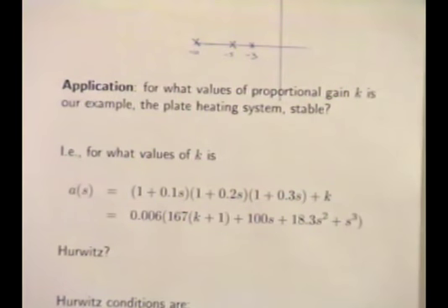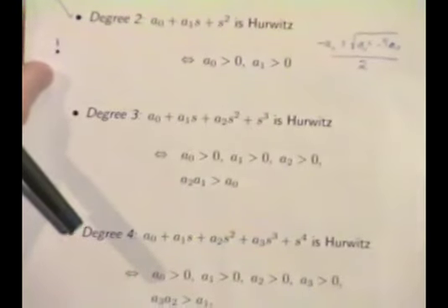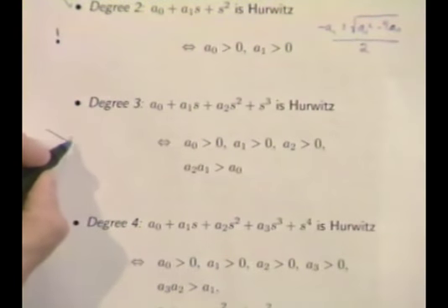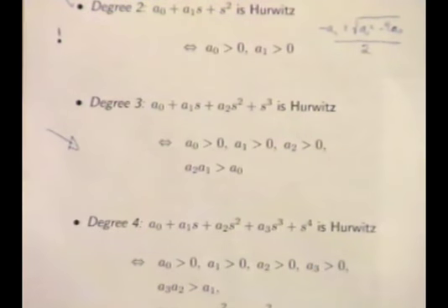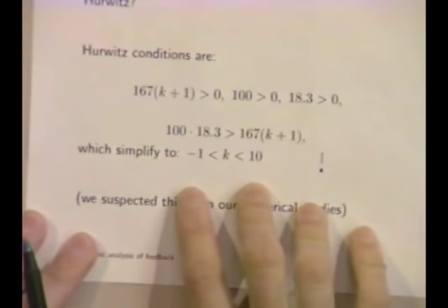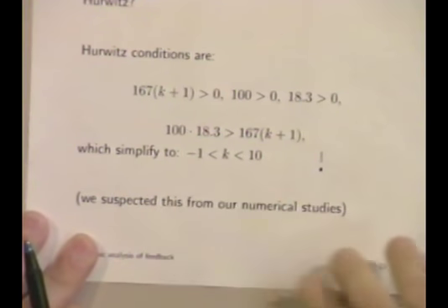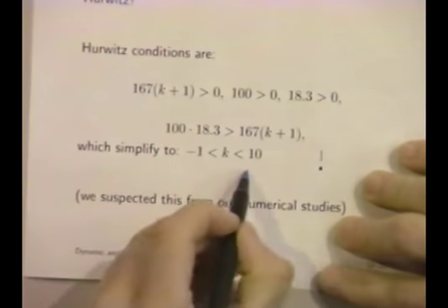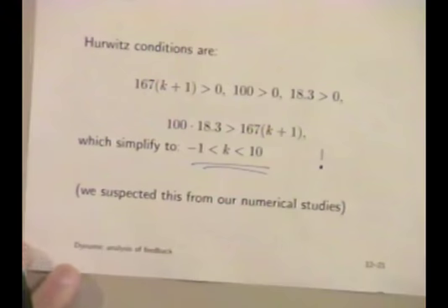So we plug in our inequalities here for 3rd order. And right away, you will find this condition for the gain of the controller. It basically says if the controller gain ranges from minus 1 to 10, you'll be stable. But anywhere outside that range, you'll be unstable.